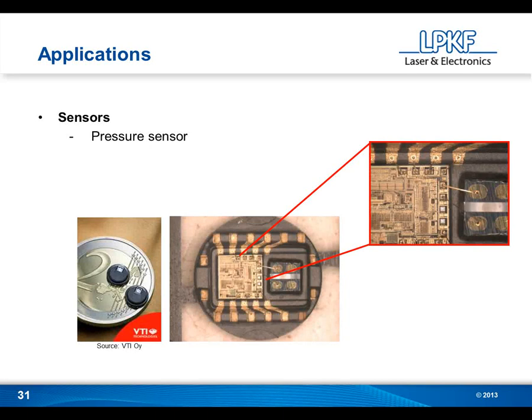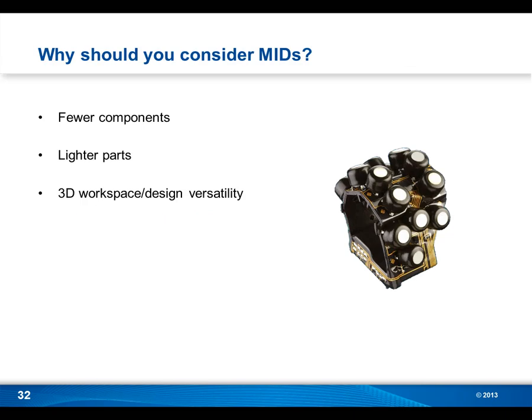So I think this particular part is using an LCP material just in order to be very, very high temperature compatible. And also, of course, the molding quality of an LCP material would allow us to make a very small, very accurate part because we don't see any shrink in the mold there. Gotcha. And then LCP is liquid crystal polymer, for those of you who were curious.